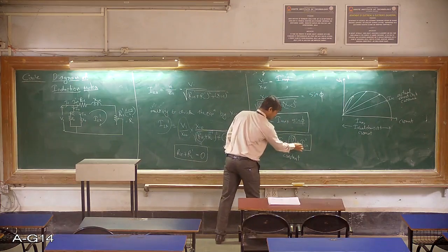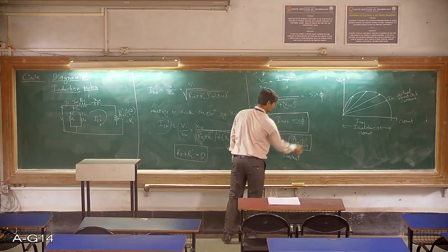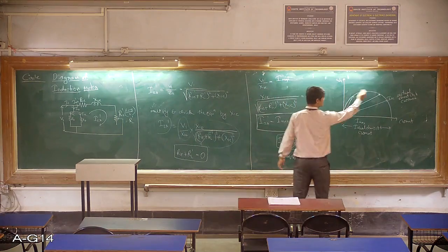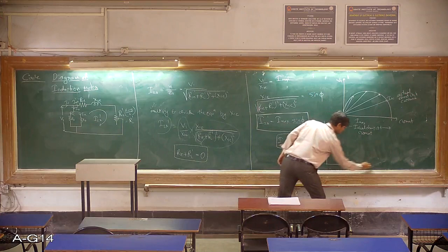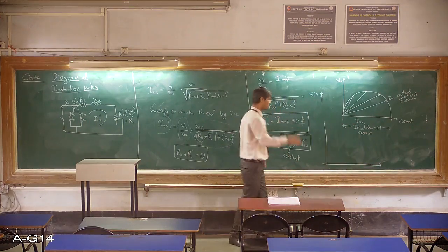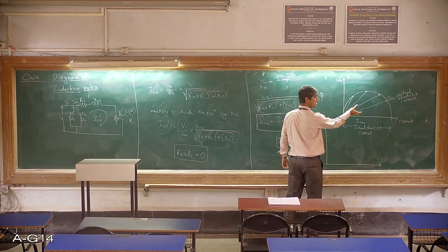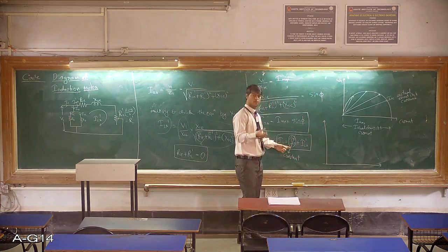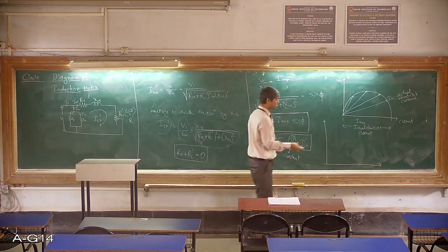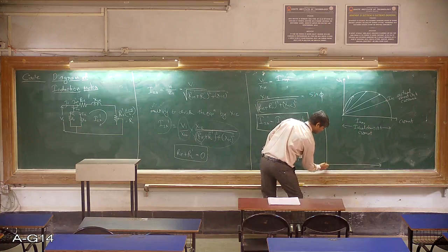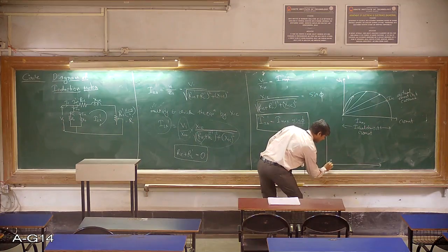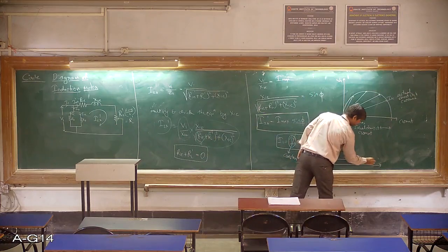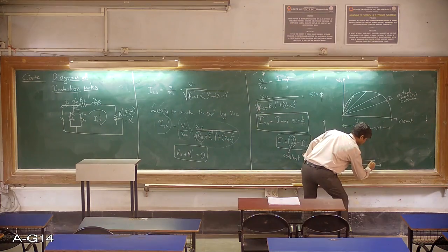Okay, it's a constant. The only thing is that I2R dash is changing. It's a variable. Because of this, the entire I1 will also change. So this circle diagram should also include this I0, which is a constant. This entire circle diagram gets shifted by the value I0, and this also depends upon the power factor. The rough circle diagram I can show you here gets shifted by a value I0, and instead of using this particular axis, we'll use a new line, whereas this will become I2R dash.